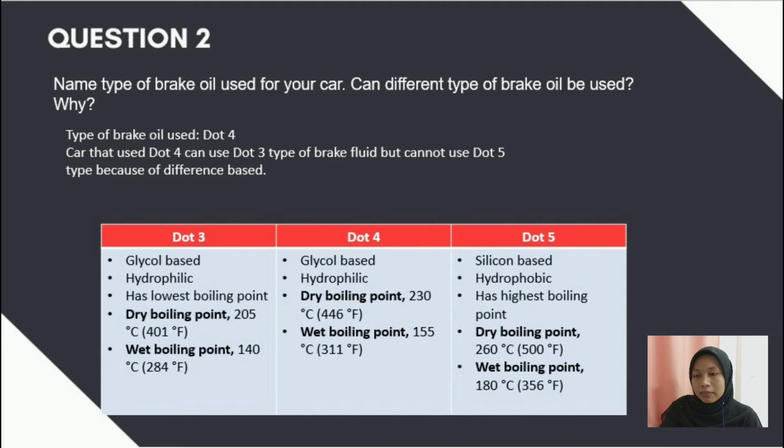Besides, the worst thing that can happen is a drop in the boiling point of the whole fluid if we mix DOT 5 with DOT 4 or DOT 5 with DOT 3. So it's not suitable for a car that uses DOT 4 to change the brake fluid to DOT 5.